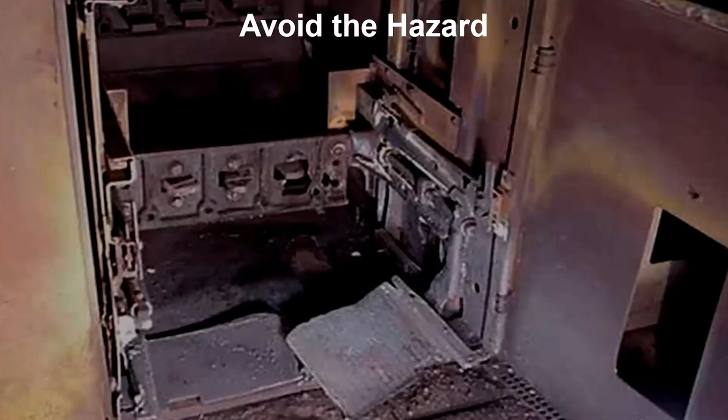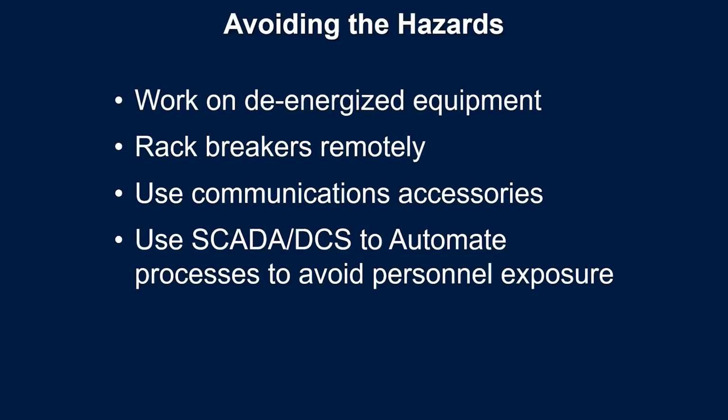And so restating that, first option, as much as possible work on de-energized equipment, and understandably it's not possible in all cases. Sometimes the equipment needs to be energized. In that case, we need to evaluate options to be able to rack the breakers remotely and use communication accessories whenever we can to perform operations such as retrieving data or sending in data and so on. A lot of times, even without human intervention, arc flash events can take place. It's not always that a mistake or using the wrong tool causes an arc flash. So we need to be aware that as much as we can, we need to minimize the exposure, and we need to minimize the amount of time we're around that energized equipment, right?